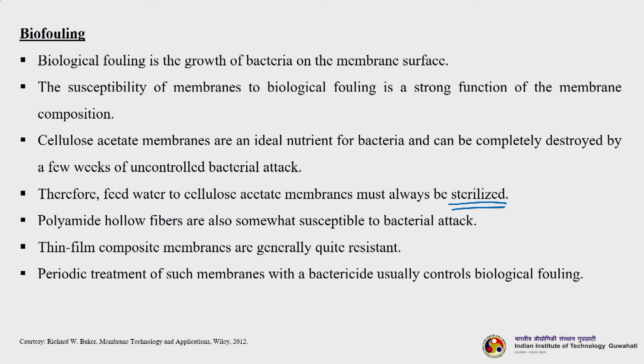Polyamide hollow fibers are also somewhat susceptible to bacterial attack, but they are less prone in comparison to cellulose acetate membranes. Thin film composite membranes are generally quite resistant, because you have an asymmetric structure, and periodic treatment of such membranes with a bactericide usually controls biological fouling.